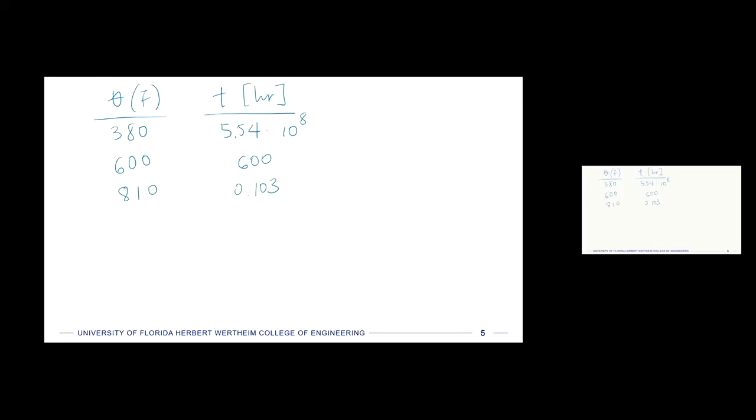which of these is the limiting factor, and then use that to calculate how many cycles we can get, right? And so for the first one, our time that we need is, I think, 1,200 hours. So if we take 5.54 times 10 to the 8th, and we divide it by 1,200, oh, I have the inverse written down here. So if our time is 1,200, I did it in sort of a cumulative damage type way, but I can do it the other way also.